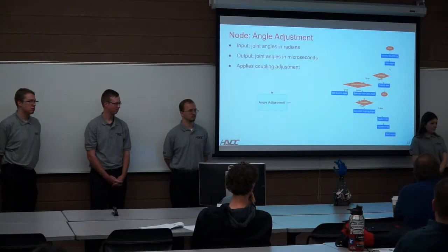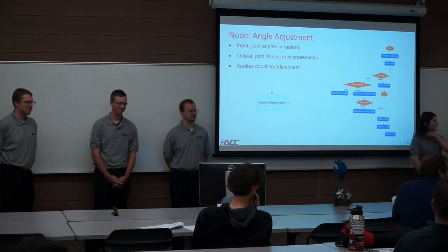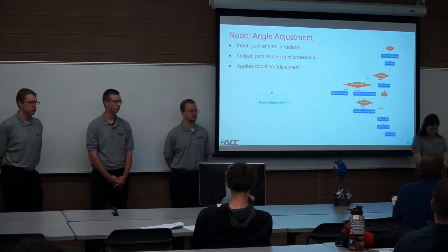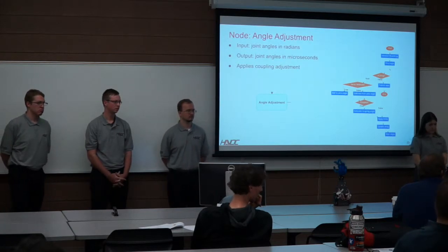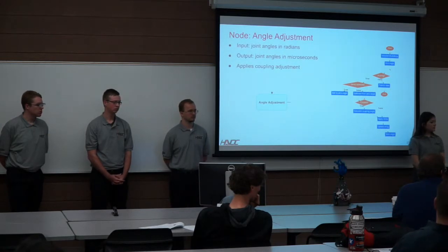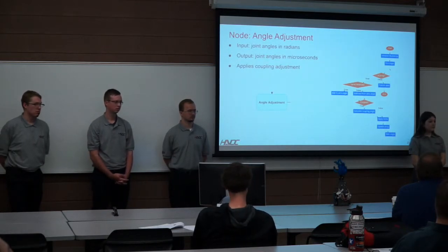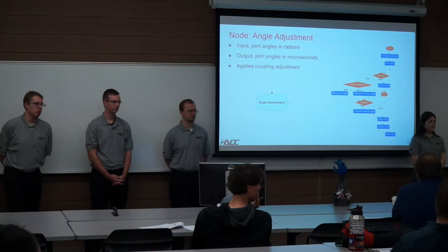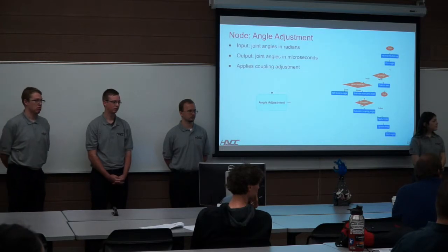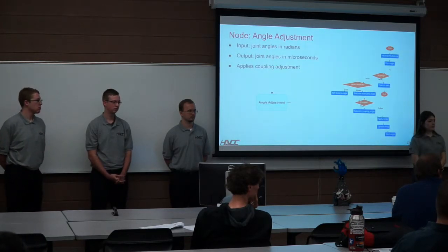Yeah, I was just thinking that you can in fact speed up your system by using feedback, so essentially. Therein lies the rub. But we didn't implement a direct control or anything because there's already PD control inside the servos. So there's some sort of controller wrapped inside the servos, but if you wanted to be able to control dynamically the motion of the fingers, you may want to go to closed loop. Yes. And at that point, the latency might cause some small problems. Yeah, but we would also have to model the PD controllers on the servos, which I think would be probably a monumental task in itself.